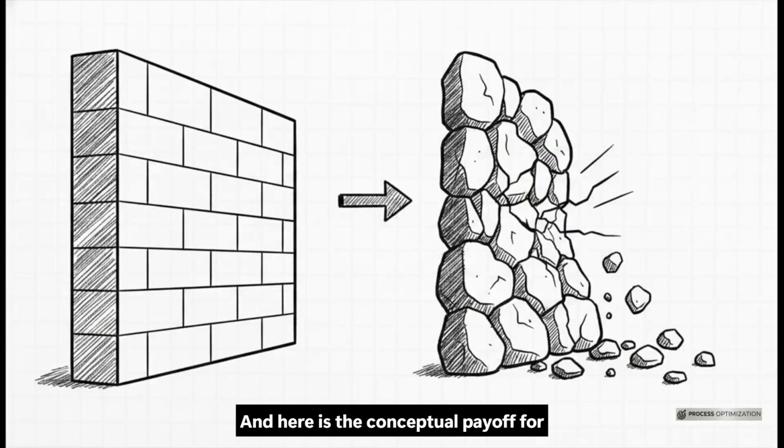And here is the conceptual payoff for our whole journey today. Because cement B has that hidden 8% of coarse chunks, it's going to fail the customer. Those coarse particles cause a much less uniform performance, which leads to lower early strength and slower hydration. This proves, without a doubt, exactly why both parameters, Blaine for surface area and residue to catch those lazy, coarse chunks, are absolutely mandatory in the cement mill.